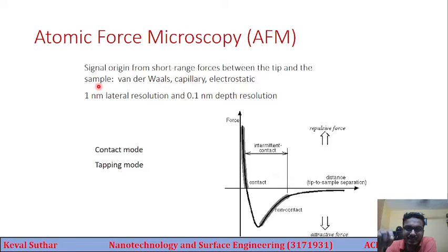So some force is applied on the sample through this tip, and we see the forces between the tip and the specimen. Like there are van der Waals force, then capillary force and electrostatic force. So these are the forces which are calculated here, and there is 1 nanometer lateral resolution and 0.1 nanometer depth resolution in this method. There are two kinds of mode. First is contact mode and second is tapping mode.